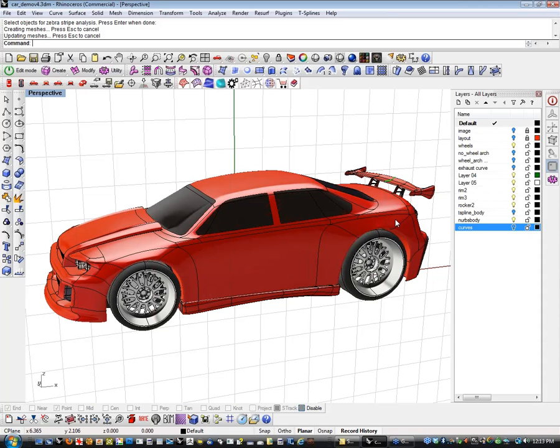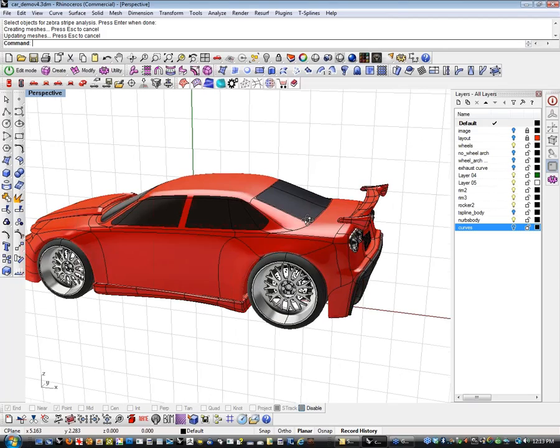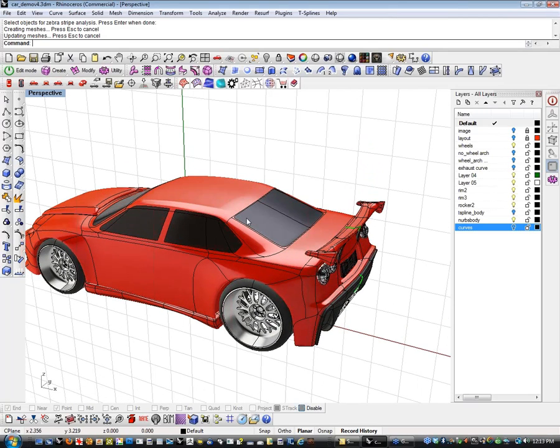And if there was any change to the model, which there always is, there's always some marketing guys going to come in and say that you need to be able to fit 7 baby seats in the back of a sports car, then you'd have to go back and model, which means you'd have to tear it all apart, which means all the transitions that you built would all be lost. You'd have to throw all those away, rechain, go back and modify all of your primary surfaces, and then go back and reblend. And that takes a considerable amount of time, because every time you tear the model apart and make a change, there's a considerable amount of rework in order to do that.